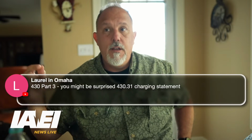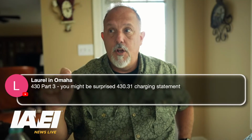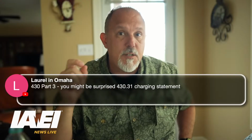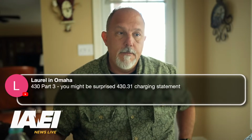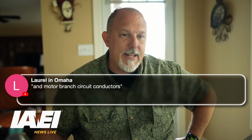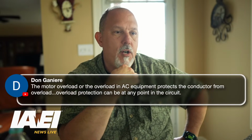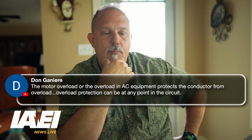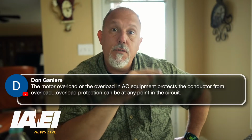That would tell you that all of the other examples do not provide protection of the conductors, the controllers, and the resistors because it doesn't specifically call it out. And motor, exactly. You're right. But the motor overload or the overload in AC equipment protects the conductor from overload. Overload protection can be at any point in the circuit. It can, Dawn, as long as it adheres to 240.